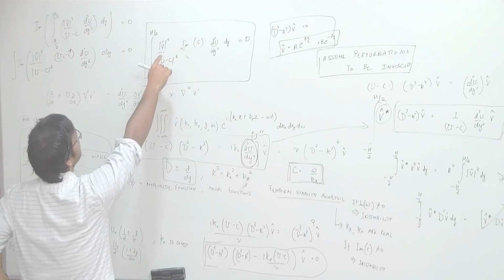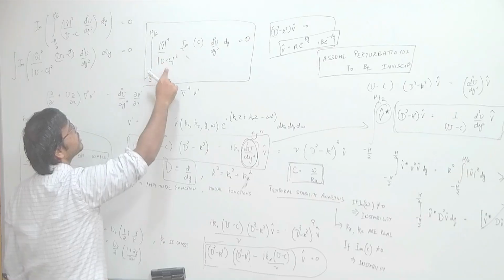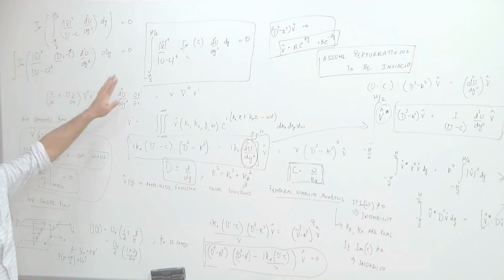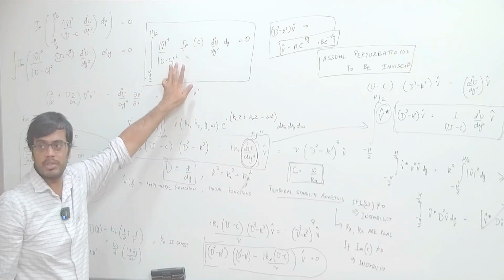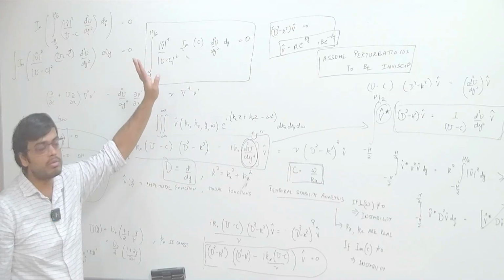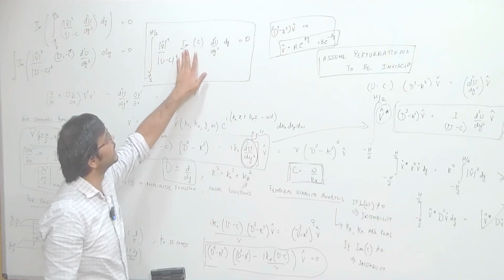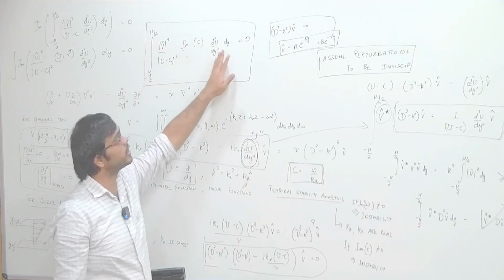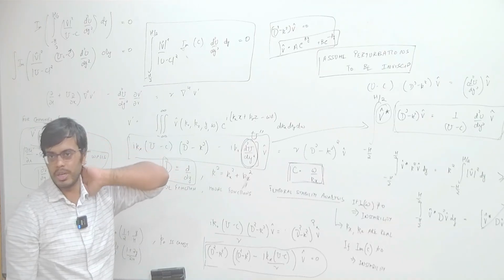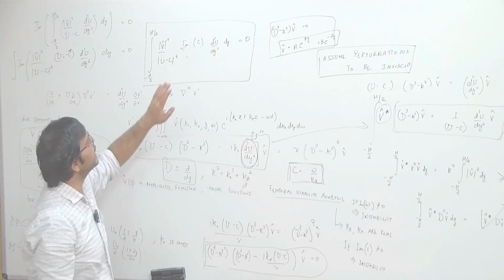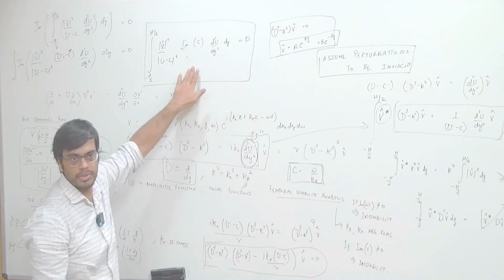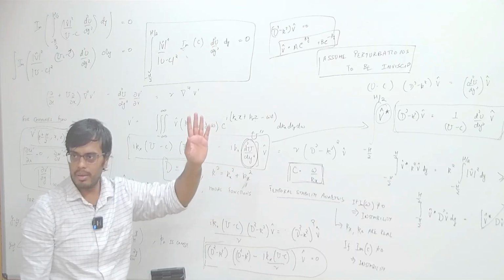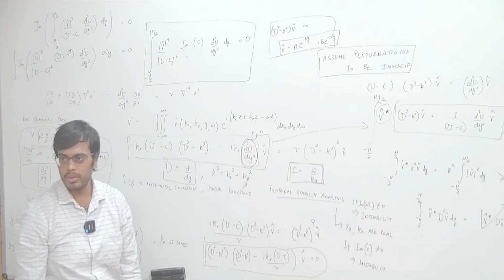Now, focus here on the left hand side, this quantity is always positive. By construction, mod v hat square by mod u minus C square is always positive. You are saying that imaginary of C times d2u by dy square times something positive, integration should be 0. Now, integration of this integrand can be 0 if it crosses some sign from minus h by 2 to h by 2, right.